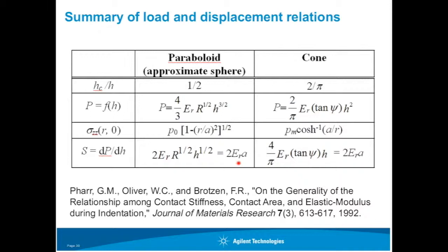It has been verified experimentally over many years that this expression holds very well for shapes that are not axisymmetric, so long as the radius of contact is more generally understood. So if you calculate an effective radius by taking the radius that would produce the same contact area that you actually have, then this expression still holds.